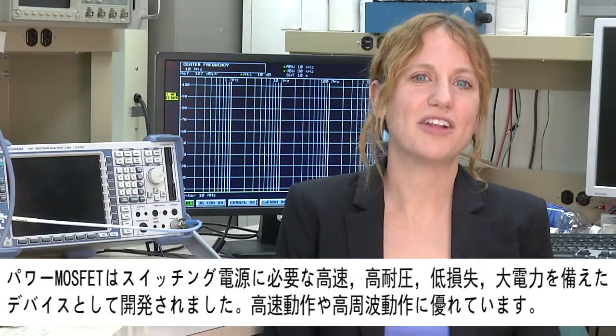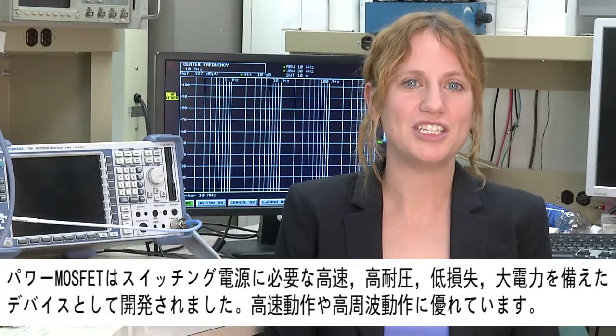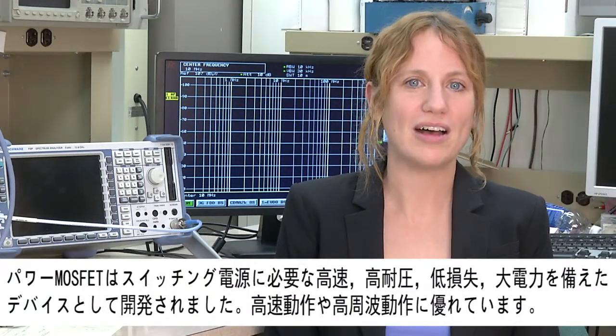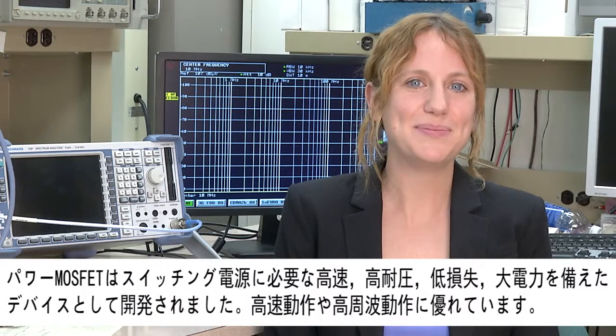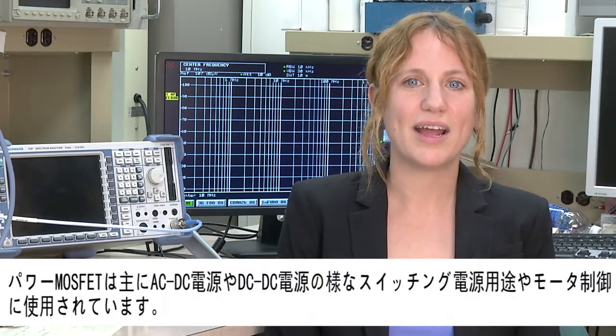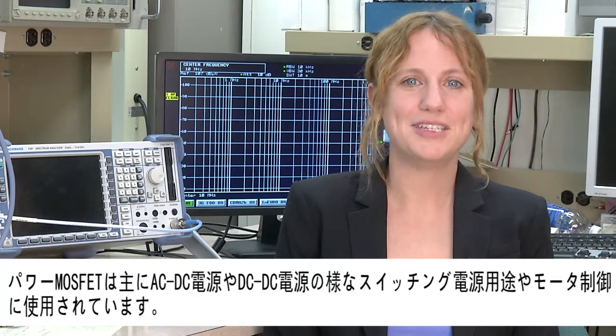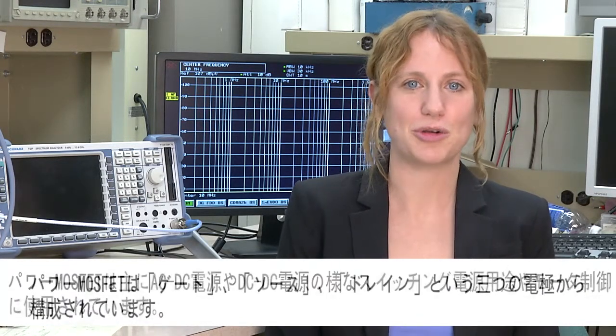Power MOSFETs offer excellent performance in high-speed switching, high breakdown voltage, high current, and low power loss. They are excellent in high-speed, high-frequency operation. Power MOSFETs are widely used in switching regulators such as AC-DC or DC-DC converters and motor controllers.